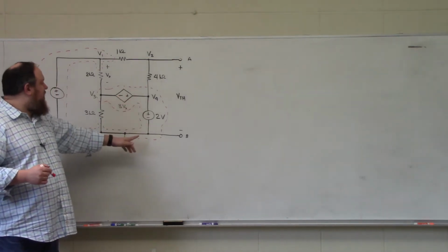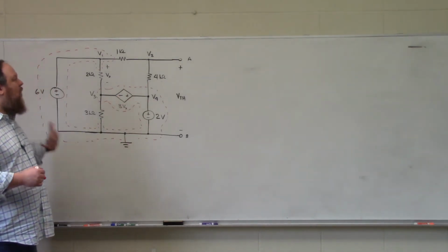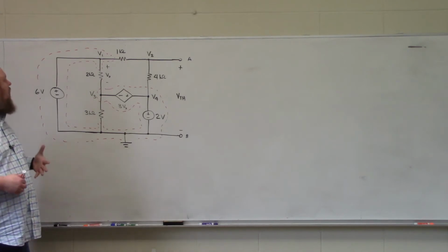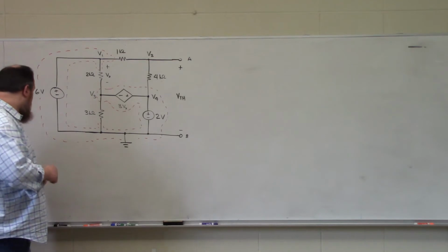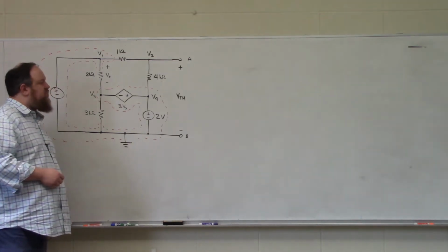Since they are connected and contain ground, I won't have to do Kirchhoff's current law at supernode 1, 3, 4. I'll only have voltage relationships.